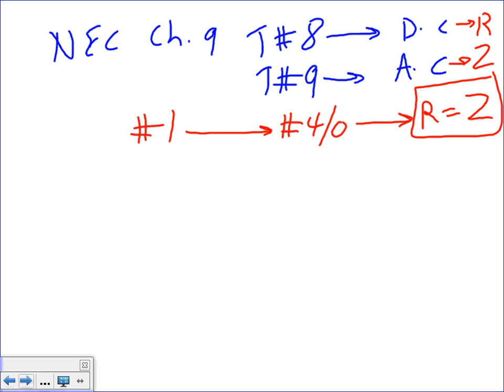What's the inductive reactance? As you move your conductor through the system, you loop them, creating a coil, right? Because the inductive reactance is the impedance of a coil. As you move your branch circuits and feeders up and down and over, you're looping them. So that creates some type of impedance for the system coming from the inductive reactance. For the most part, we're going to assume that they're the same now and use only table 8.